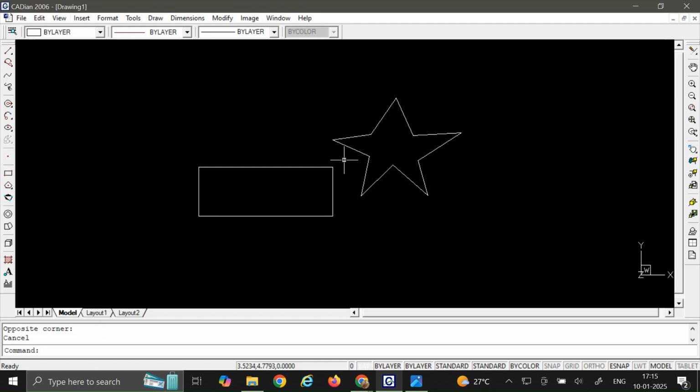It is the move command. Okay, so move is basically used to move a single entity, right? What I mean by single entity is, as I told you here, this star diagram is created with 10 different lines. But if I use pan, I'm going to move only this complete star diagram. But if I want to use this single line alone, then I'll be using move command. I hope you understand the difference.